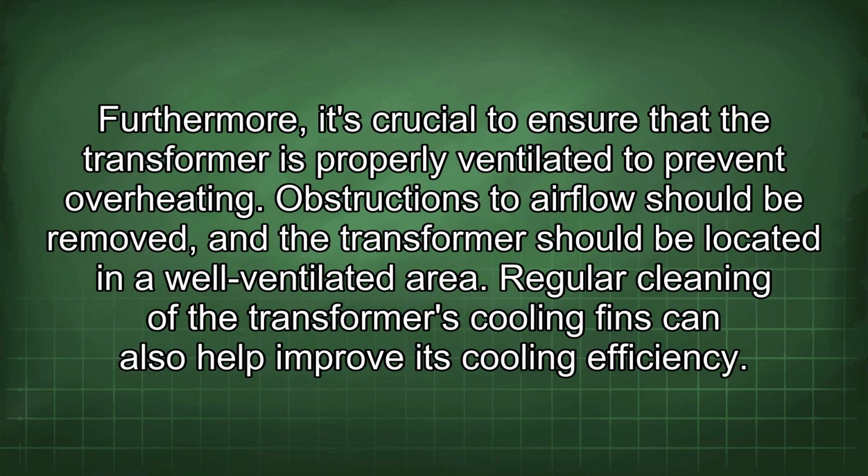Furthermore, it's crucial to ensure that the transformer is properly ventilated to prevent overheating. Obstructions to airflow should be removed, and the transformer should be located in a well-ventilated area. Regular cleaning of the transformer's cooling fins can also help improve its cooling efficiency.